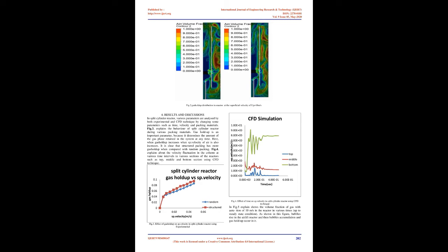3. Modeling. In this work, the Euler-Euler method and VOF model based on the two-fluid system was applied. Furthermore, each fluid was assumed to be a continuous phase in each part of the control volume. The phases were dispersed in the interior spaces and diffused within it.